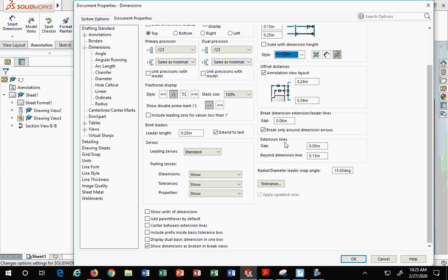You're in class, see me visually moving my left and right arms toward the object I'm dimensioning. Those are the lines that extend from the dimension to the object I'm dimensioning. The tapping you guys are hearing online, that's me hitting the monitor on the side, which is where the speaker is attached. Sorry. The gap for the extension line from the object is going to be 0.125. I want that extension line of my dimension line not too close to my object. Beyond dimension line is going to be the exact opposite, 0.0625. Okay?